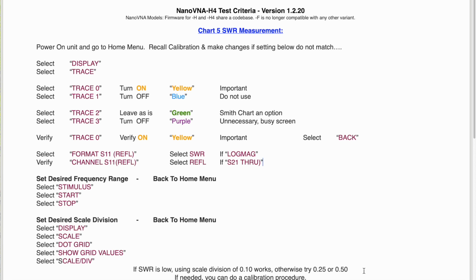Okay, measuring the standing wave ratio, coaxial loss, maybe even lengths, impedance, stuff like that. But I would say the standing wave ratio is probably the most common use measurement for radio operators, especially ham radio operators, because they have multiple bands and multiple antennas, and many do make their own antennas or modify existing ones. In fact, I have a vertical antenna that arrived, and I will be testing that in the near future.